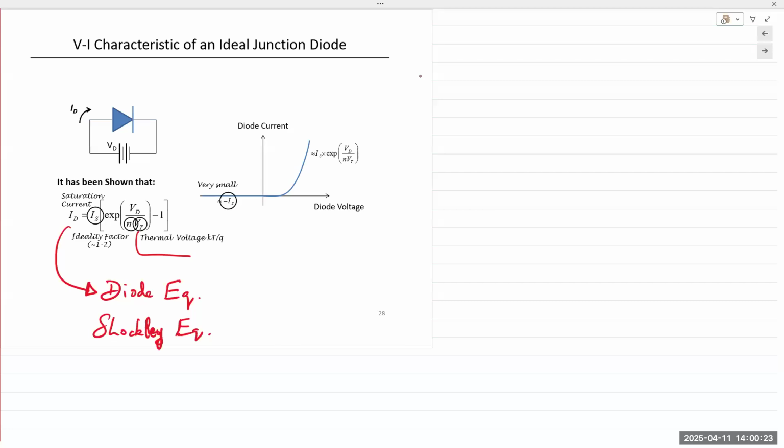So the relationship typically breaks down to diode current ID equals IS, the saturation current, times e raised to VD over VT. That's it, and it's a good approximation. Even though we ignore many of the quantities, this is a good approximation. So the diode current is proportional to the exponent of the voltage that you apply. This is the relationship between the diode voltage and the diode current.